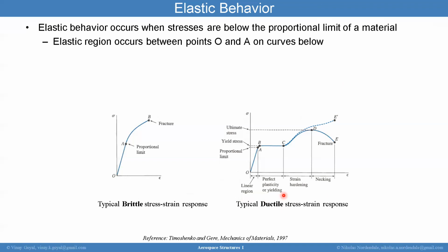And that's important because it's often that students, and even some practicing engineers, get lulled into a sense that all metals are ductile, and that is not technically true. We'll get into that on a later slide: metals can behave ductile, and metals can behave brittle. It depends on a number of things, including their environment and loading type.